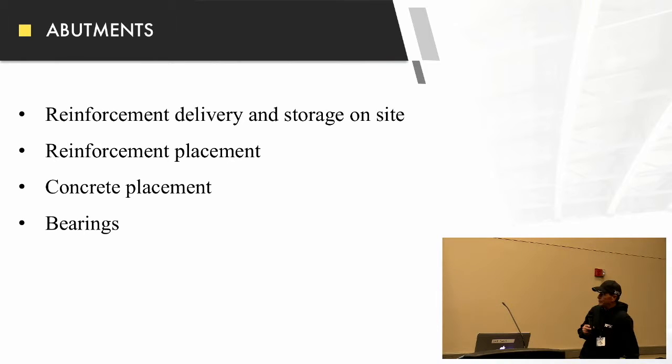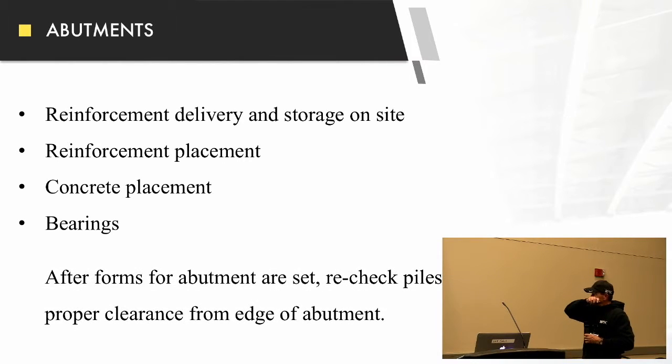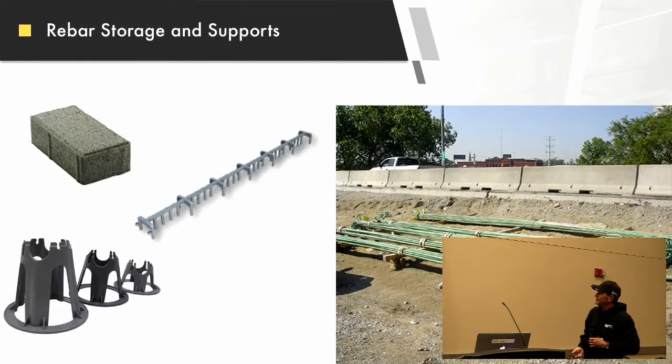Rebar placement, concrete placement, and then bearings on your abutments and stuff is a huge deal, I think, that many people don't pay enough attention to, because they figure it's just a piece of rubber up there that just has to be there, and it's not just a piece of rubber. Again, recheck your piles after the forms have been placed.